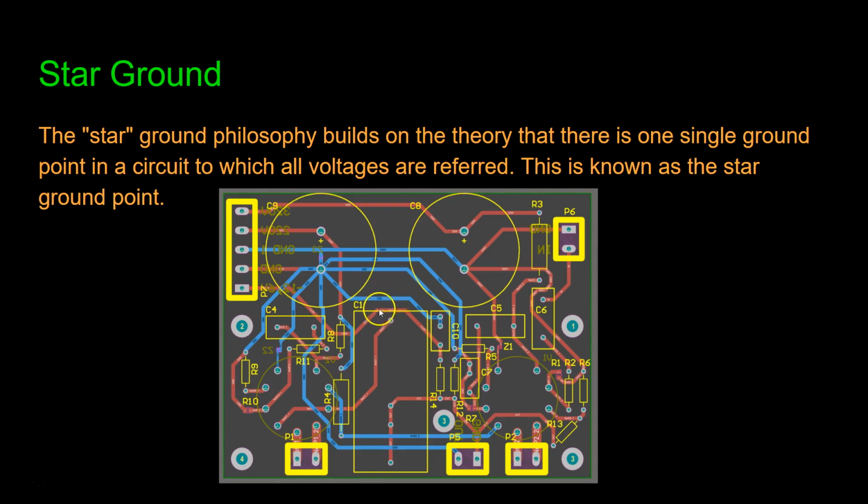This particular problem can often be avoided by having separate power supplies and separate planes for the various circuit portions.